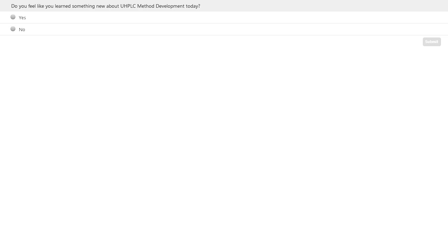We actually have a nice ACE application knowledge note on how to do that. And there is a tab within the translation tool that walks you through the method. You basically run a gradient with acetone, and it shows you, then you work out the midpoint, and it gives you a value for your dwell volume. So I'd again encourage you to have a look on the resources section for that knowledge note.